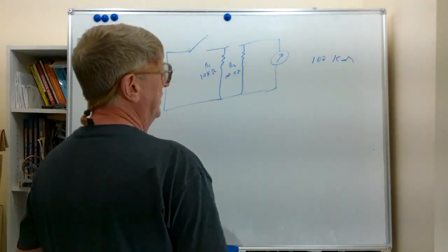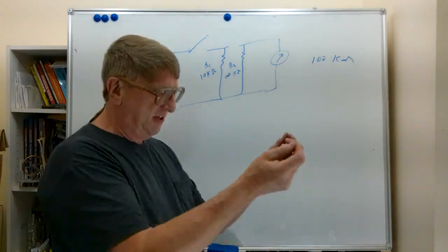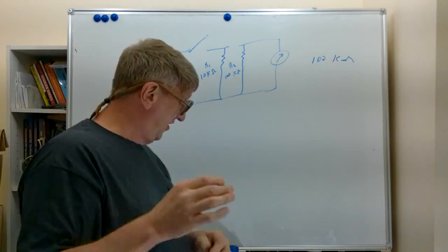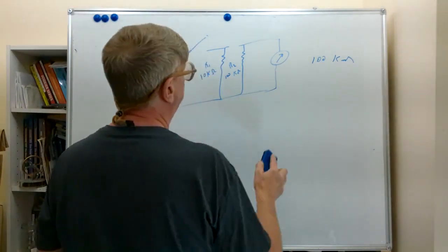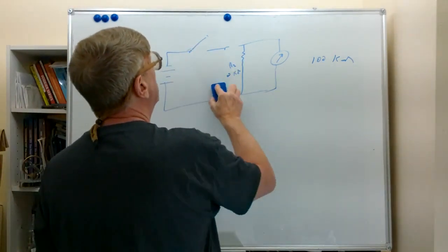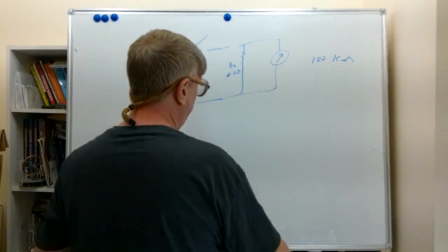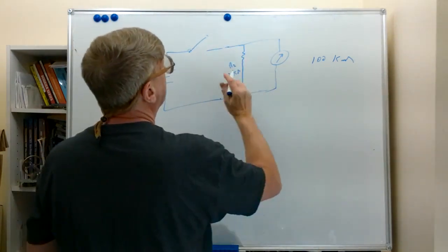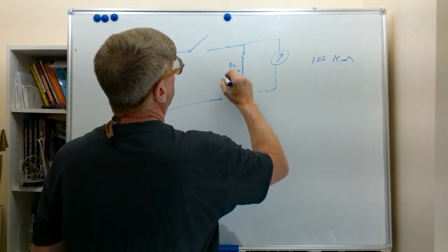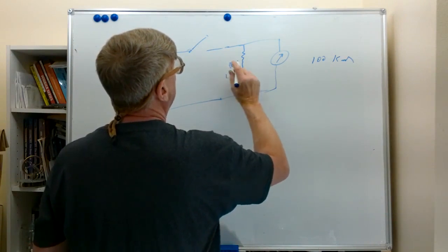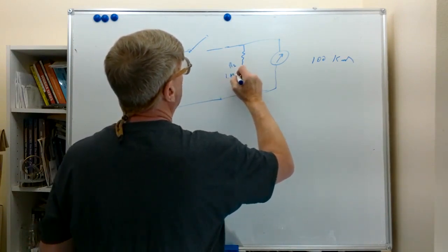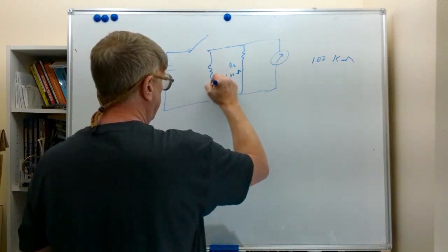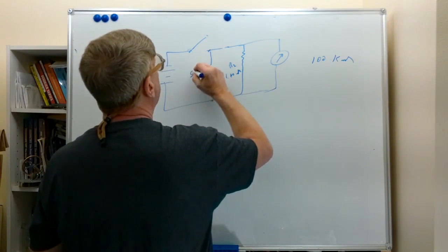And if you're reading resistors with your ohm meter, say they're just in your hand, you do not want to put your fingers on the leads of the ohm meter, not because you're going to get shocked, because the ohm meter puts out a very low voltage for this testing, but if this was, say, a 1 meg ohm resistor that you're reading, and you touch here and here, well, your body might have a resistance of 50 k or so.